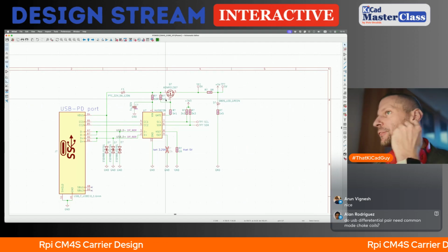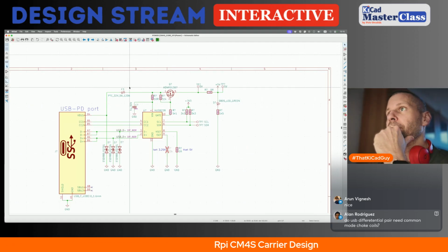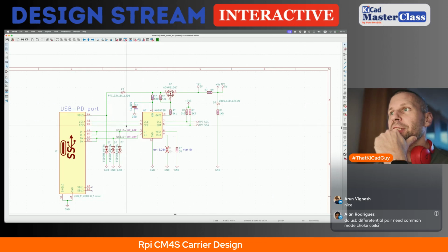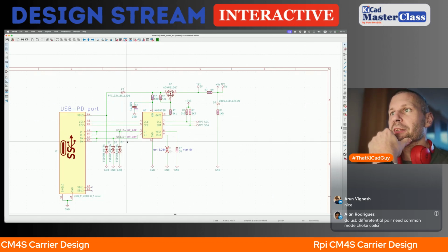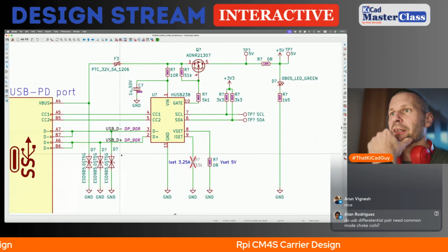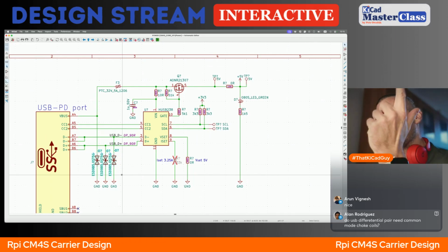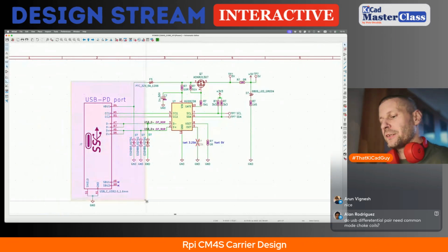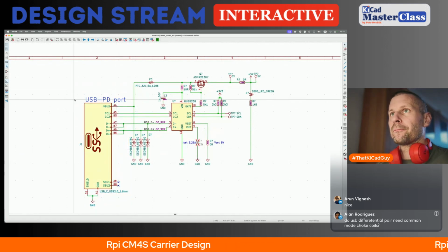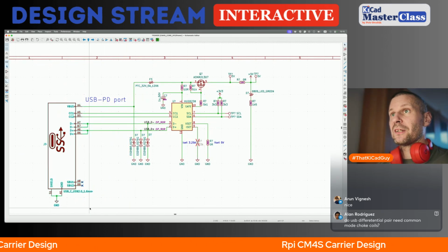Okay, we have MOSFET, we have powering of the IC, we have CC, we have USB D minus on D minus, D plus on D plus, assigned net classes, ESD diodes on both, on all, not on all. We have to add 2 more because we have CC1 and CC2, which are signals of the same sensitivity as the other ones.